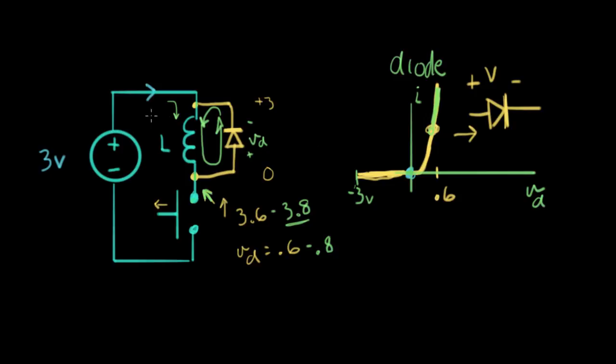So the effect of having this voltage go way north is called kickback. That's kickback from an inductor. This diode is a protection diode, and basically what it does is it supplies a pathway for that inductor current when this voltage goes above the top end of the inductor.